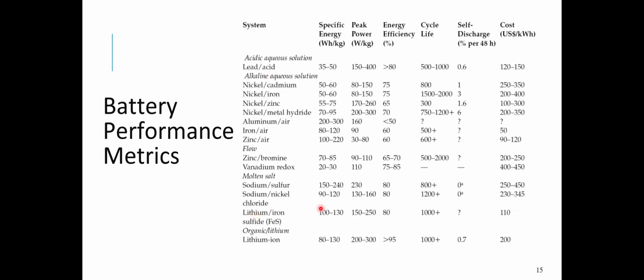chemistries here that have, for example, extremely high specific energy, like zinc air. Typically, air batteries have high specific energy because there's no electrolyte, but they have relatively low cycle life and they're very difficult to make. So right now, lithium-ion batteries are winning the day, but in the future, we might switch to another chemistry, just like we switched from lead acid to lithium-ion batteries.